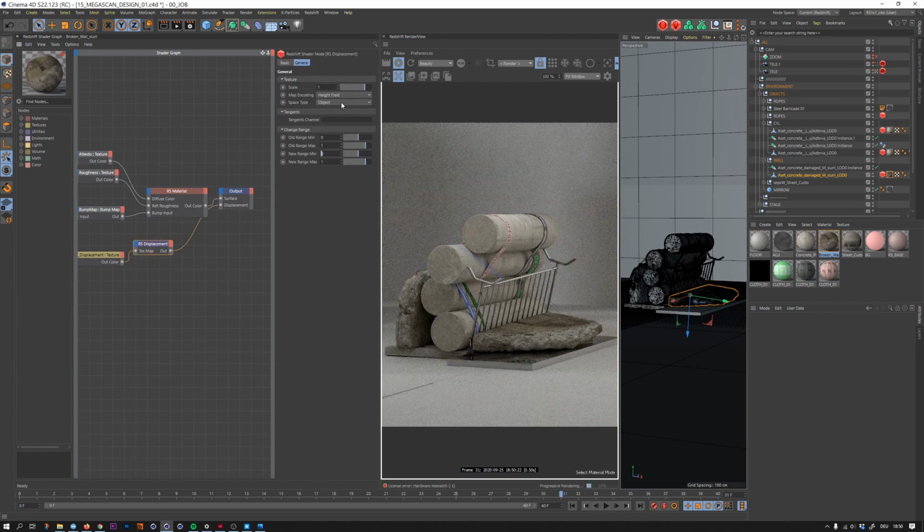And same again, or let's even extrude it a little bit. So I'm going minus 0.45 and plus 0.55. So it's extruding a little bit. That's still, or even more, 0.4, 0.6. Because sometimes I found that when you go 0.5, 0.5, the displacement sometimes gets weird. So I find that it often looks a bit better if there's a little bit of positive displacement.